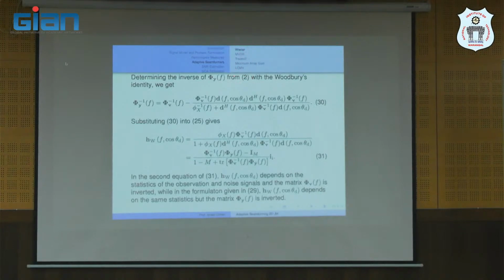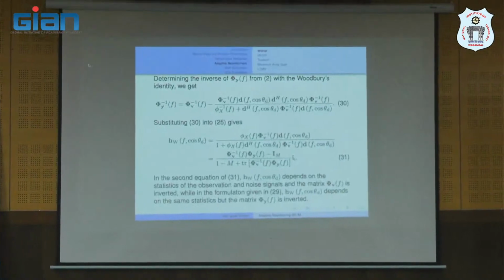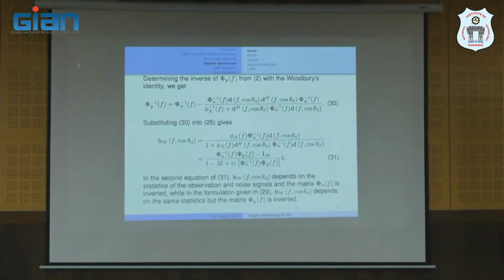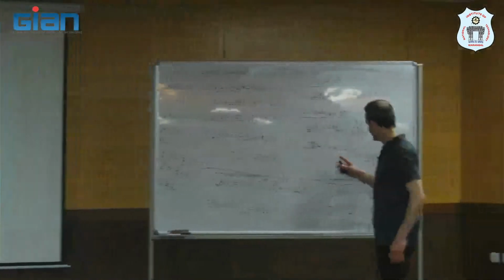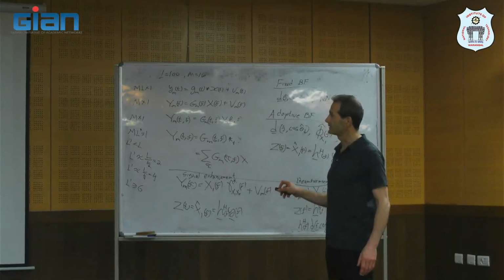These methods are similar to signal enhancement. Just the difference, instead of the steering vector, which is based on the relative transfer function, we will use a steering vector for directions. No reflections in the environment. See, so all these expressions will be very similar. But we can also verify what happens to the beam pattern and so on. Here we work with beam pattern. So we can see what happens to the beam patterns for different adaptive optimal filters.